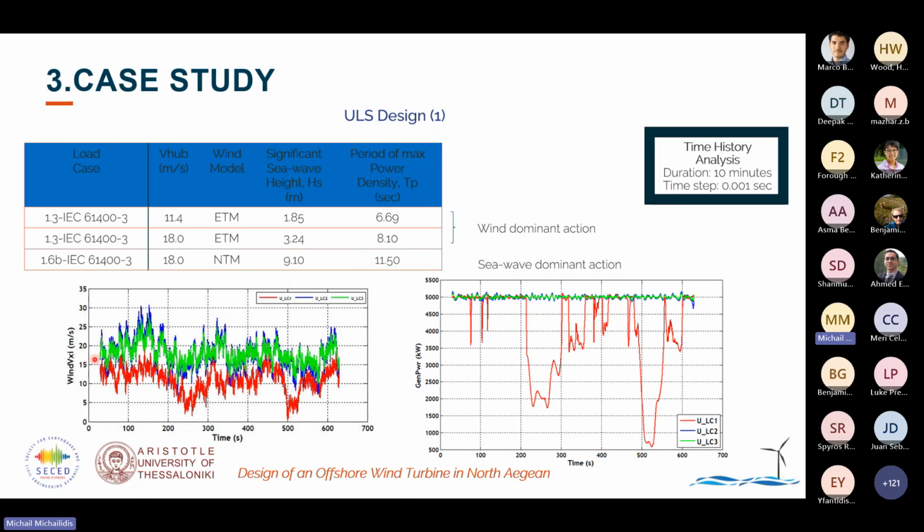You can see on the left hand the wind series for the cases that we have at 18 meters per second, with these fluctuations. The blue one gets bigger values due to the extreme turbulence mode, while the green one has smaller values as being the normal one. Both of these cases are those providing the constant power production of 5 megawatt, which is the power production of reference.